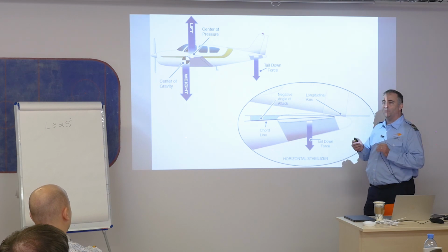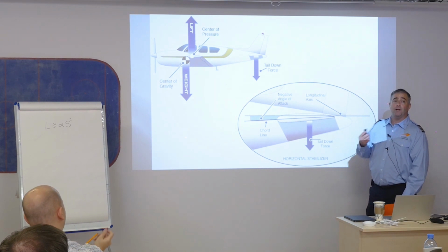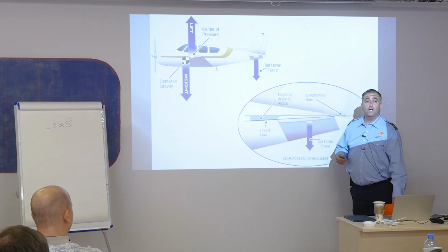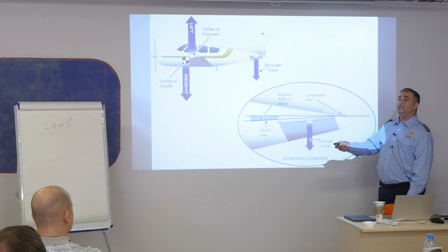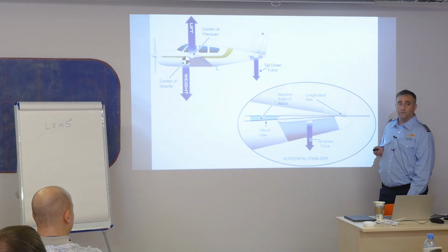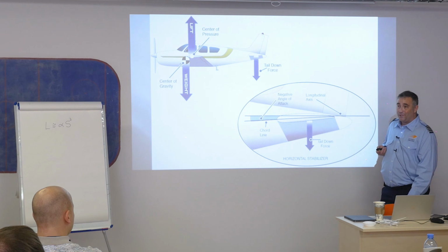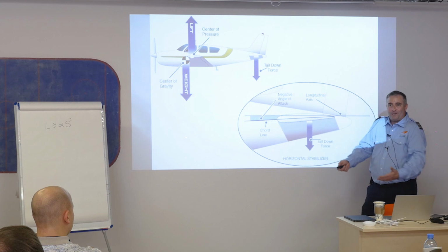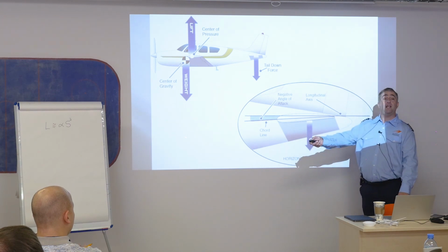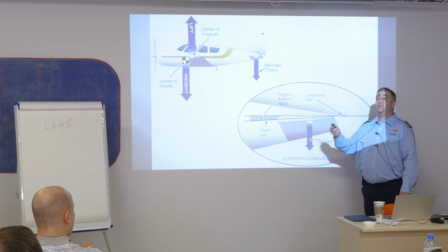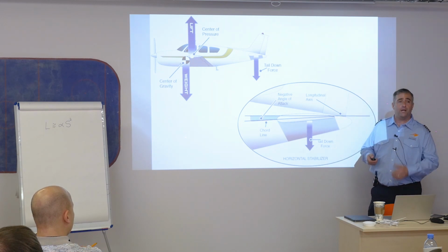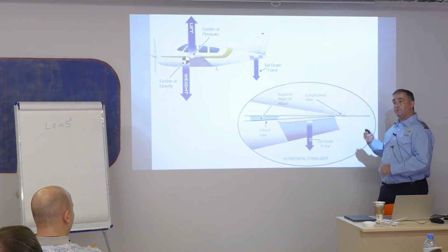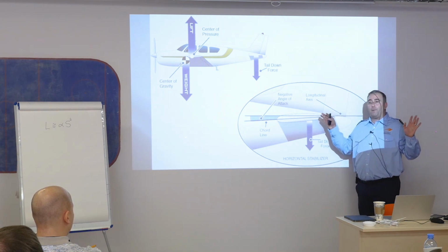Okay, everything was equal, now I change it. And I'm going to do that in my example, and we'll do the same thing in the airplane to demonstrate stability. I'll do that in my example by decreasing my power setting, okay? Which I think is a terrible way to begin a descent, because I usually want to keep the power as fast as possible. I'm trying to get somewhere here, man. But in this example, just for training purposes, I'm going to decrease my power setting. Because I'm in a carbureted model airplane, I'm going to put on the carburetor heat first, apply that, and then decrease my power setting. Okay, so I've reduced the power in the airplane.